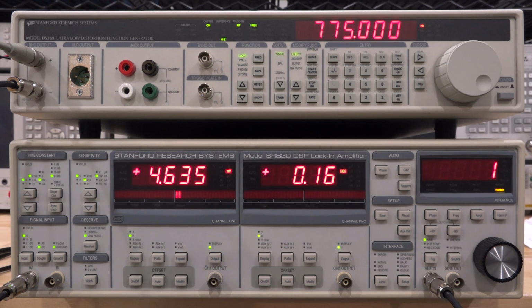Now, in order for us to be meticulous in our measurement, we also need to make sure that the response of the filter is correct for the second, third, and so on harmonics. And based on the filter response, we expect about a 9 dB attenuation on the second harmonic, because the filter, of course, isn't perfect and is going to have some drop at higher frequencies. And we need to measure that to make sure that is also correct, and we need to undo that effect when we're measuring the THD.